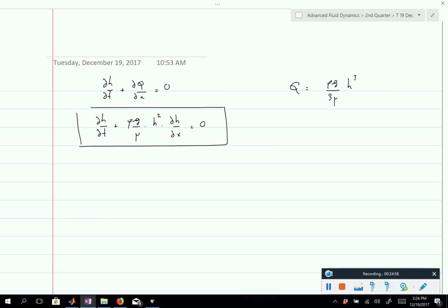Right? So note that here the only thing which is unknown, whatever we were looking for from the beginning, when we're looking at our wall, is the shape or the thickness of my paint layer. This is h as a function of x and t, and this is the equation that tells you how h changes. This is a PDE, which determines the evolution of the height as a function of time. It's a PDE in time and position x. And we're assuming that the flow is 2D.